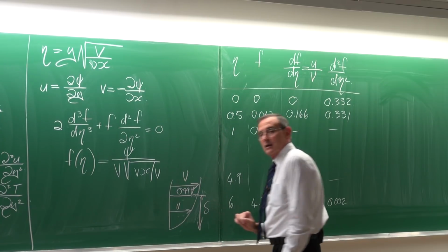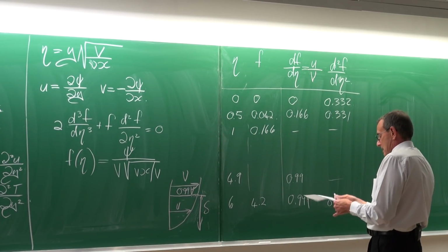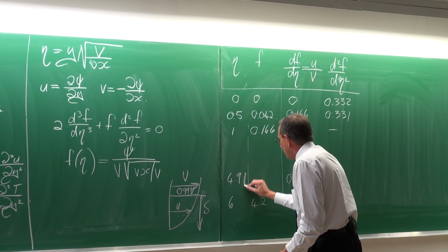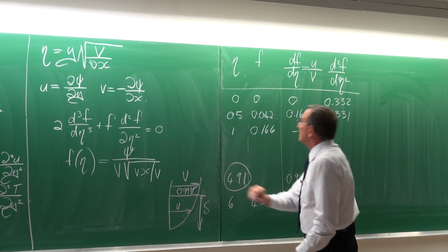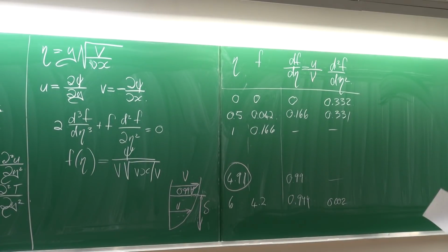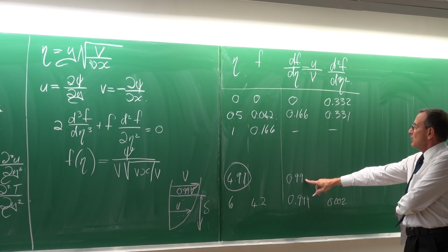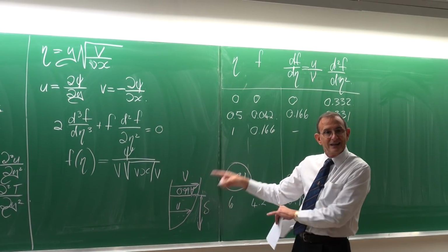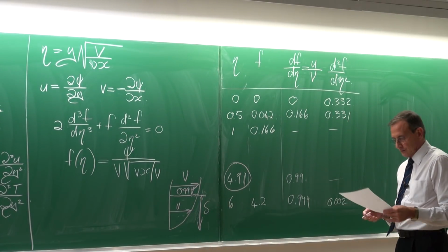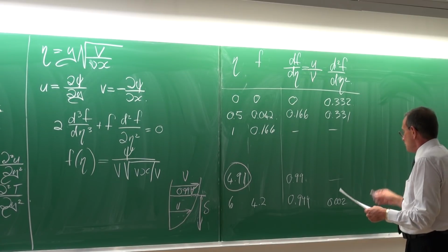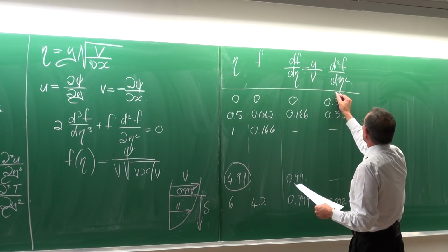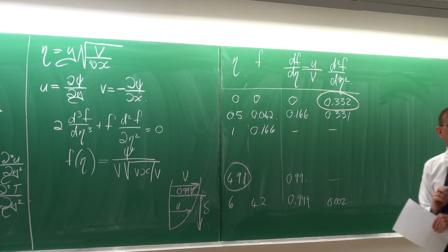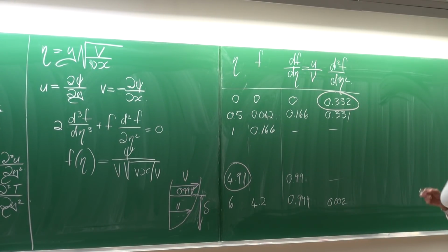So that's the boundary layer thickness. So he realized that this eta value of 4.91 is where the velocity distribution gives the boundary layer thickness. That is what he figured out. So that was the first thing that he figured out. And then there's something else there, a value of 0.332, which is also special, and I'm going to get to that just now.